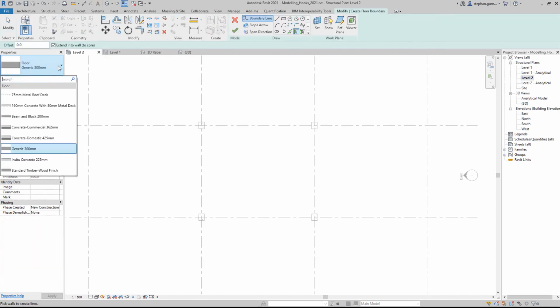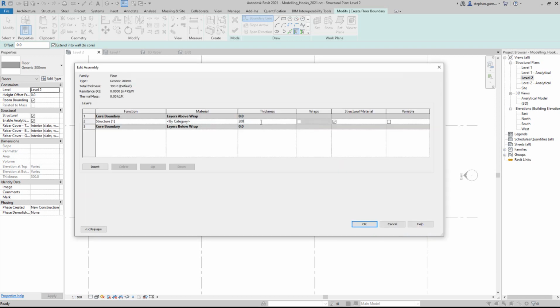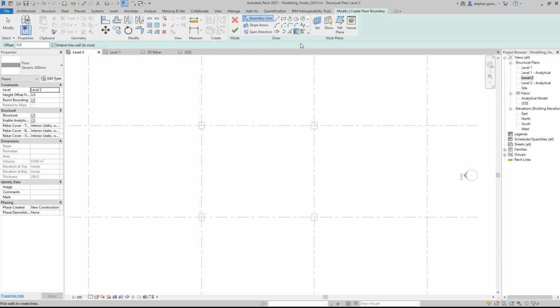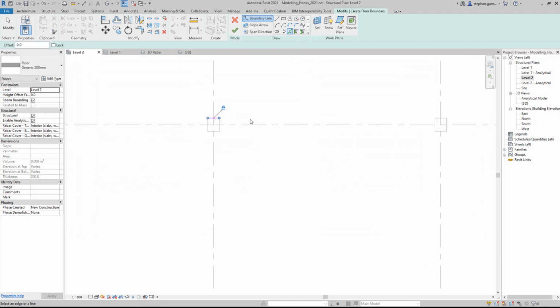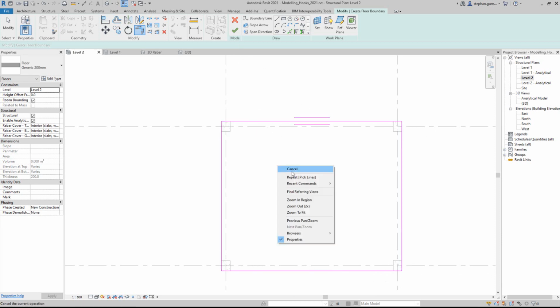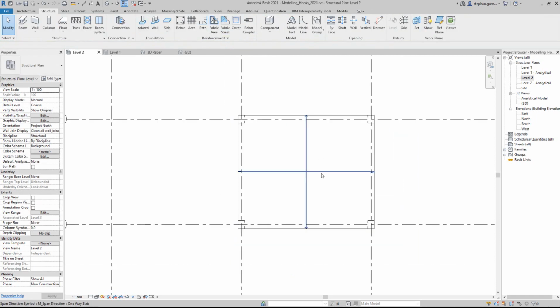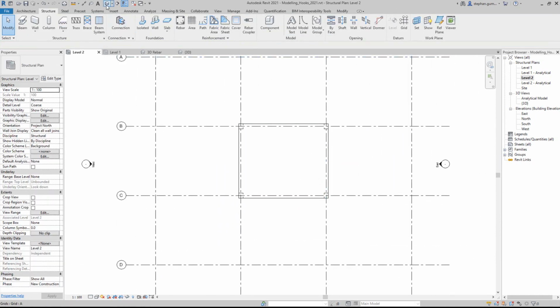Then finally, to cap it off, we're going to sit down and actually create the slab that's on top of those 4 columns, giving us the capability to be able to visualize something in the space of our model, just for reference. So what I first do is I select the edges and lock them to the face of the concrete columns, and then I go and fillet those edges, making sure to choose our span direction as well, noticing that all the edges are constrained to the size of those columns that are in that view.